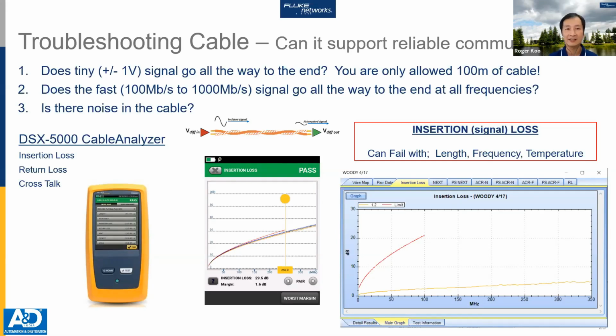How fast will this signal go across all the frequencies that we tested? Is there noise in this cable? If you look at the wiring here, we are looking at a signal transmitted on one pair and seeing how much is being received over at the destination. So that's insertion loss.